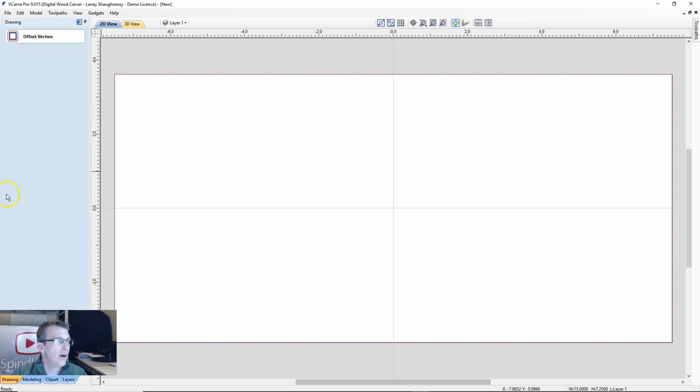We're going to offset this inward from itself a certain distance, and this is where my border is going to be carved. And I would like a 1-inch offset. So we're going to go for a distance of 1 inch. And you don't have to type in 100, a solid number 1 will be fine. Or you can, if you want to get into the habit of the 100, that's fine as well.